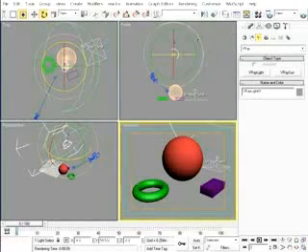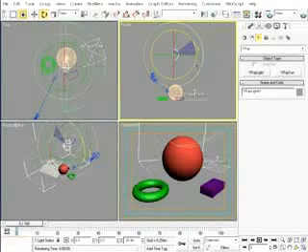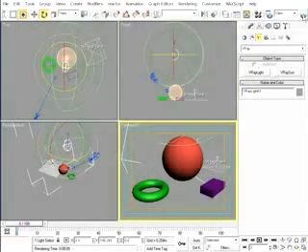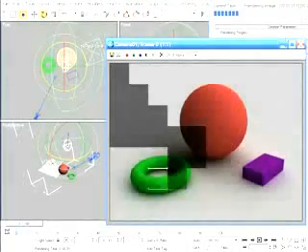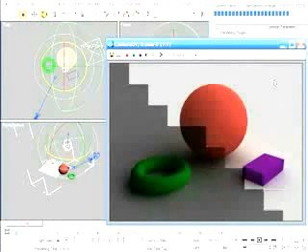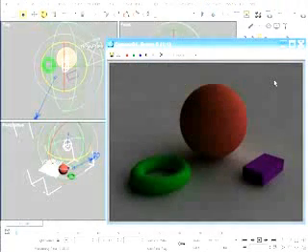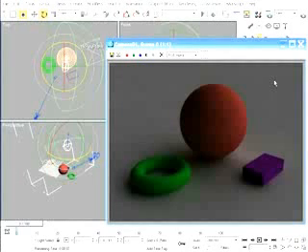And I can even rotate the VRay dome light even more so that it's pointed upward slightly. Now when I render, I get a kind of skylight that you would see if the sun were below the horizon, getting ready to turn into a nighttime scene.